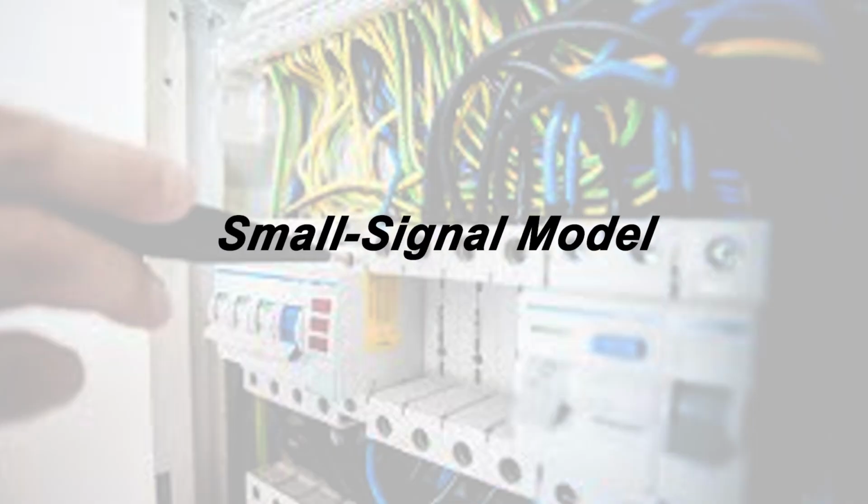The first step is the small signal model. To perform AC analysis, we first create a small signal model of the differential amplifier. This involves replacing all DC sources, such as DC biasing voltage or current, with a ground reference and considering only the AC variation around the DC operating point.